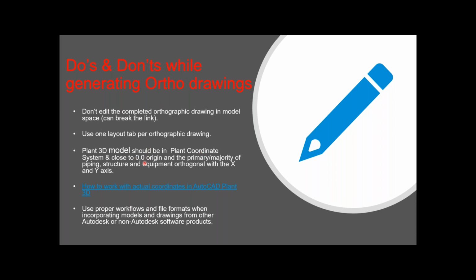So keep your external reference drawing at the origin. Do not keep it far away from your origin. And primarily, the majority of your piping, structure and equipment data, you should definitely keep close to the origin,